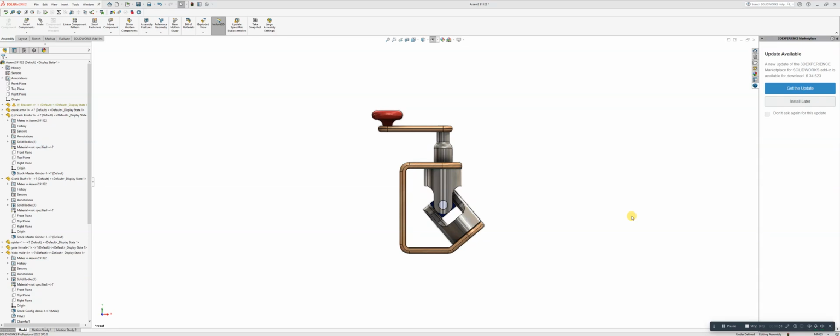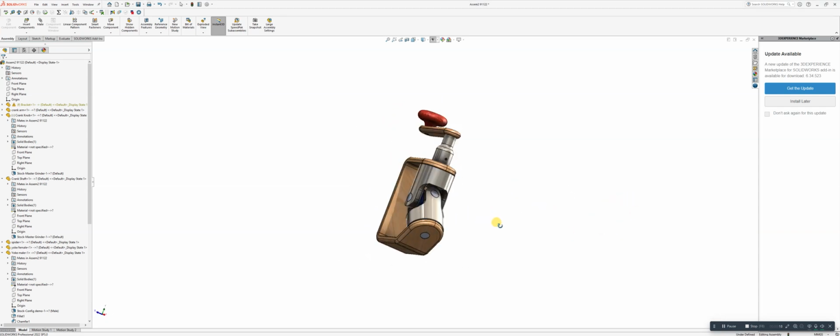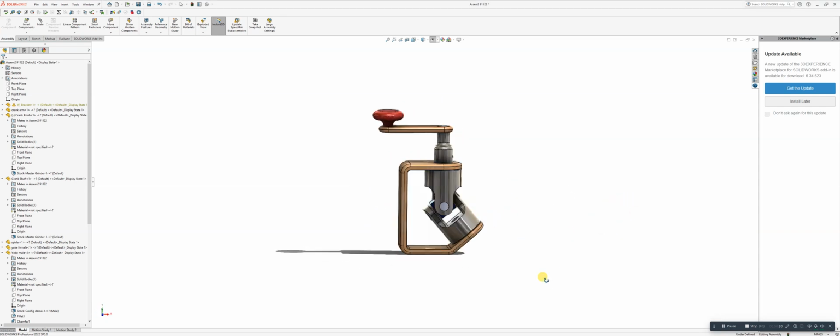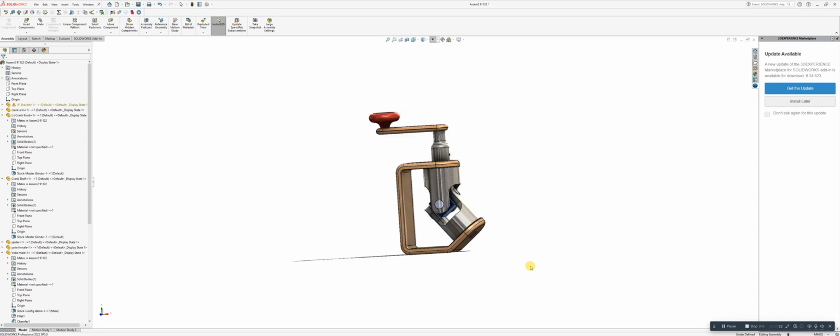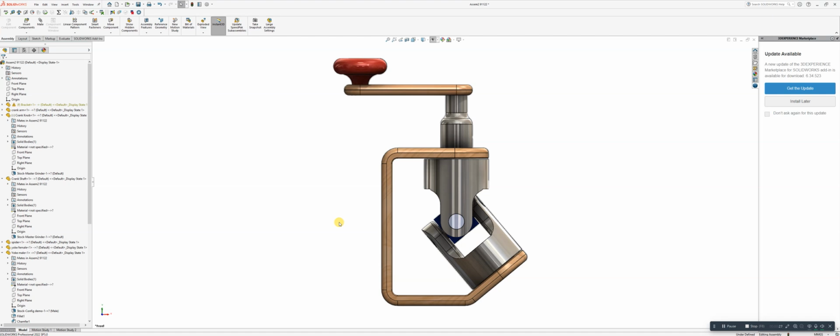Okay, I'm going to talk about creating a general arrangement drawing. If I take the UVJ as an example, I have a side elevation view there. I would suggest, I'll just rotate it around, this is from the assembly, and it's not a component drawing. So I'm going to press the space bar and I'm just going to go and use that side elevation.